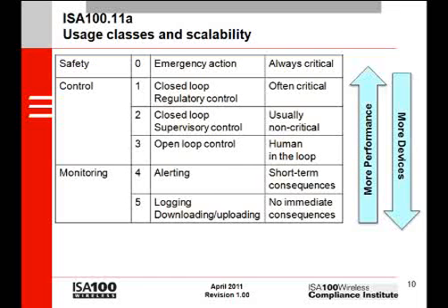The single device being used for a Class 1 application will typically need more network resources and performance than another device used for Class 5 applications. This is indicated by the arrow labeled more performance. It is also anticipated that there will be more devices used for monitoring than for control, potentially tens of thousands of devices in a plant. This is indicated by the arrow labeled more devices.